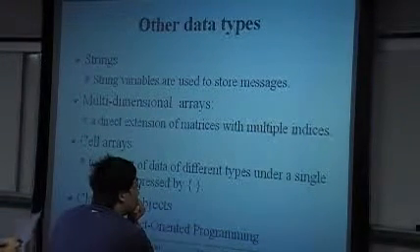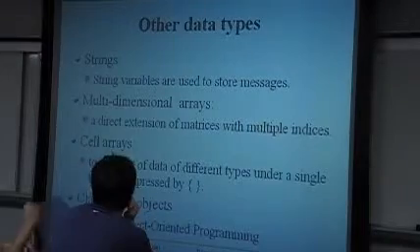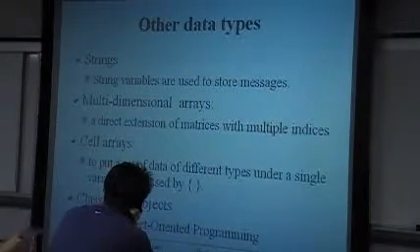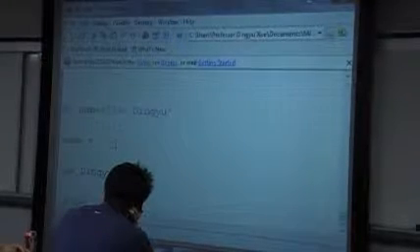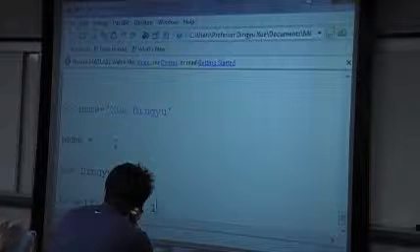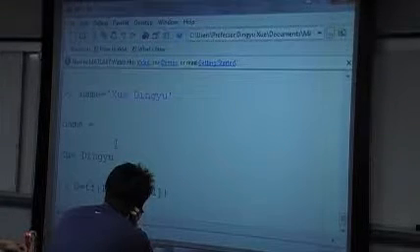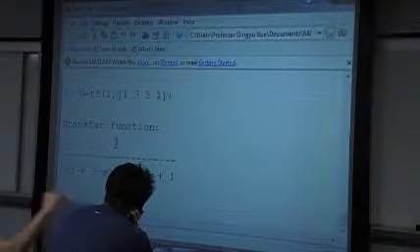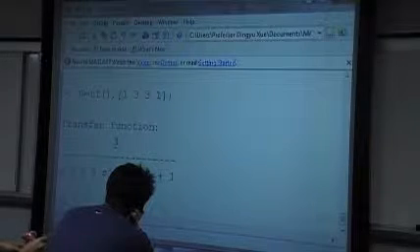It is defined in a class or object space, so that if you want to represent a transfer function, you can use a command like this: 1, 1, 3, 3, 1. And this is the transfer function, which is 1 over (s plus 1) cubed.